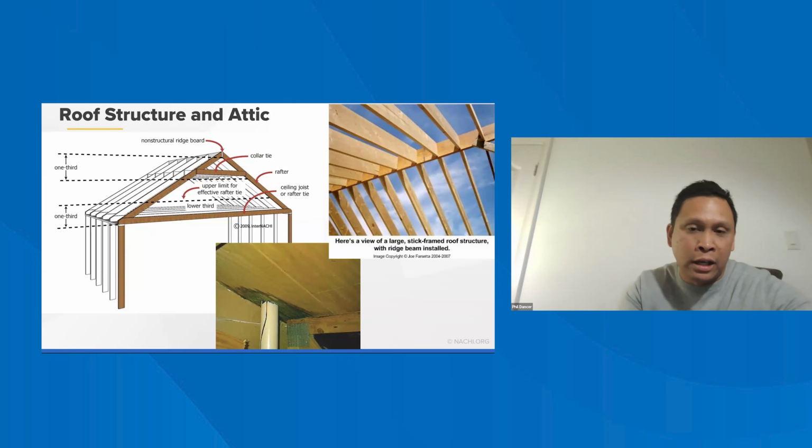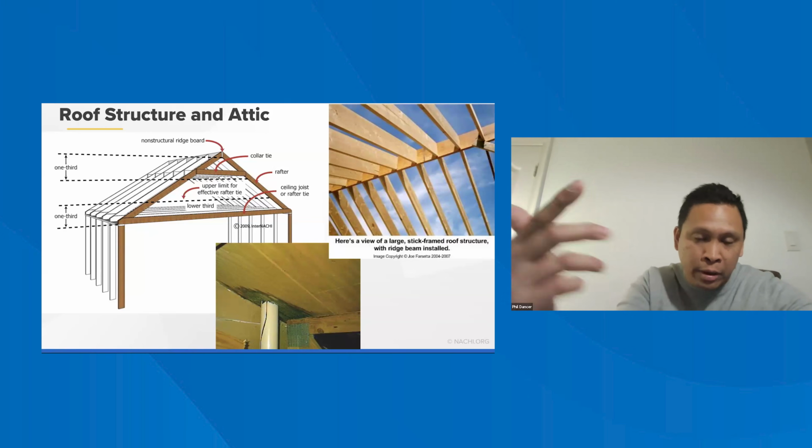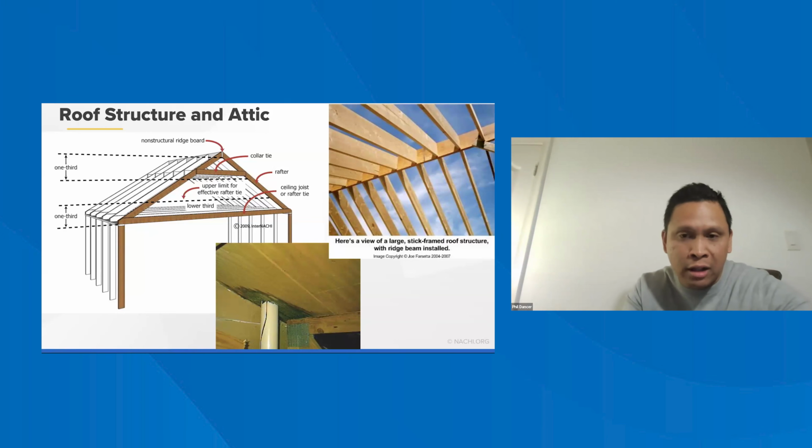Expecting to see nails that are actually being sealed. I'm hoping not to see that the top of the boot has collapsed inwards, so it is concave versus convex. If it has collapsed inward, so concave, it's harder for water to drain out, which could explain the reason why the water is staying there.